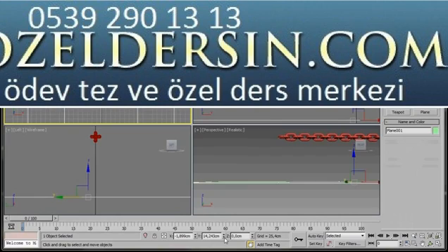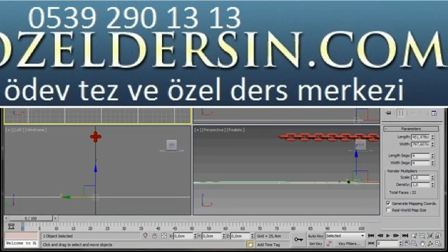I'll drop down to the transform panel at the bottom of the screen and bring my X and Y axis back to 0. This will just center the object. Then I'll come over to the modify panel and I'm just going to bring the length and width segments back to 1. That's alright, we'll just leave that as it is.